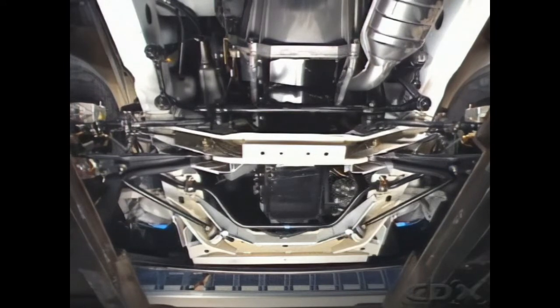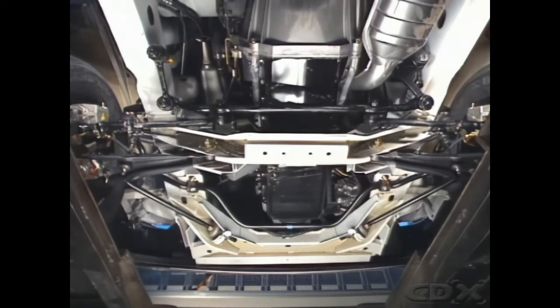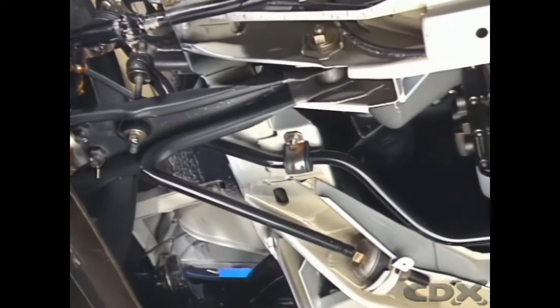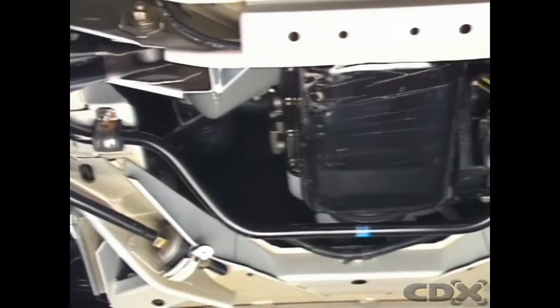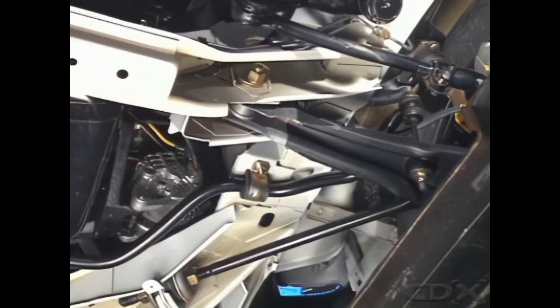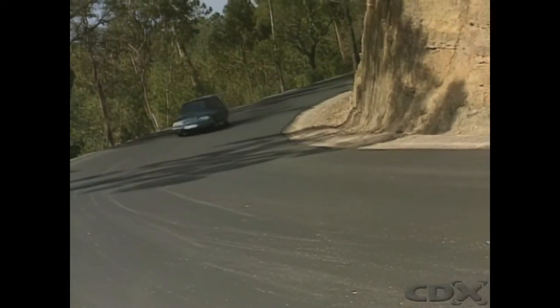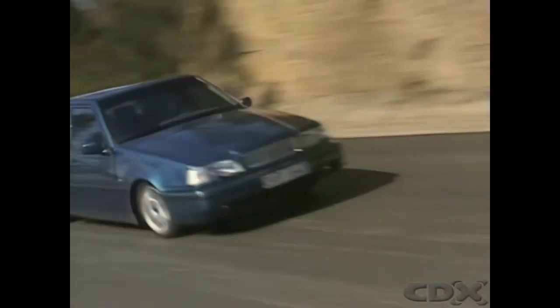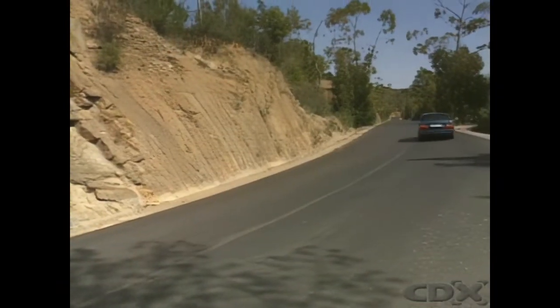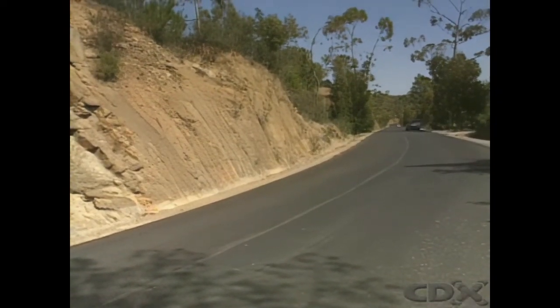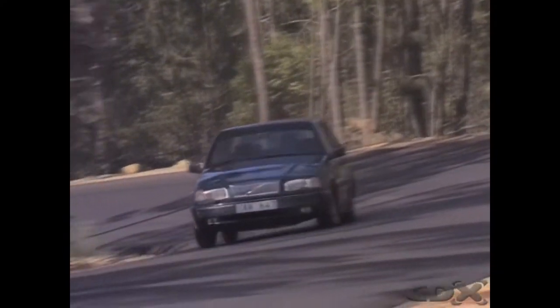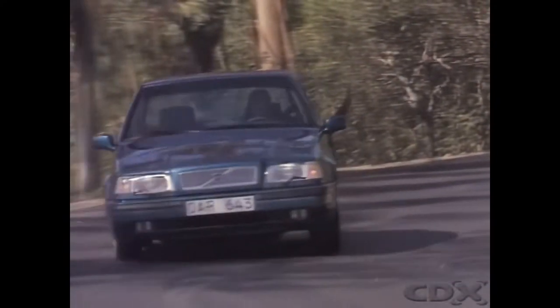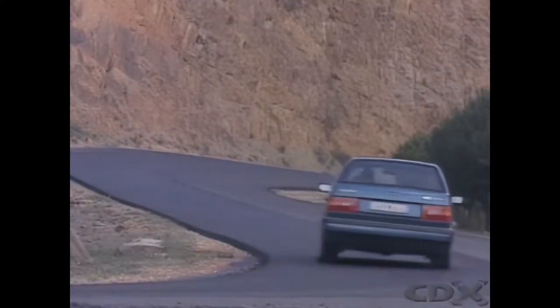It's used in light vehicles as a stabilizer or anti-roll bar, connected between each side of the suspension on the front and sometimes the rear. When the vehicle is turning, centrifugal force acts on the body and tends to make it lean outwards. The anti-roll bar, or stabilizer, tries to use its connections to each side of the suspension to resist this roll tendency.